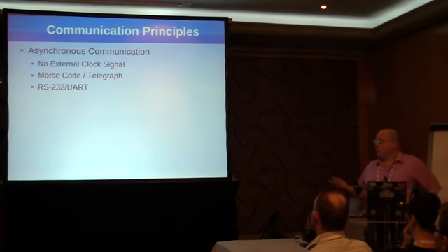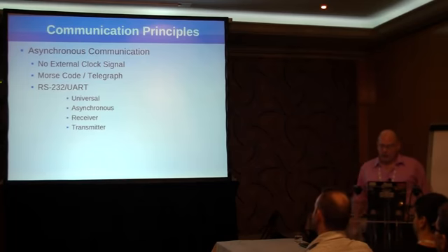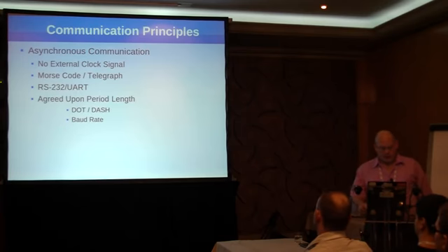Another common asynchronous protocol is RS-232. Most everyone in here has probably used RS-232 at one time or another. And the fact that it is a UART, a universal asynchronous receiver and transmitter. So everyone's been familiar with setting up a device where you had to have your host PC at one baud rate and your device that you're connecting to at another.